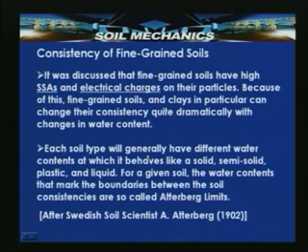Each soil type will generally have different water contents at which it behaves like a solid, semi-solid, plastic and liquid. The solid state is like a brick. For a given soil, the water contents that mark the boundaries between the soil consistencies are called Atterberg limits, after the Swedish soil scientist A. Atterberg, 1902. Going forward, we will see how the Atterberg limits are defined and how they are determined.